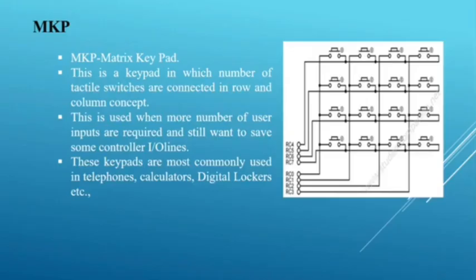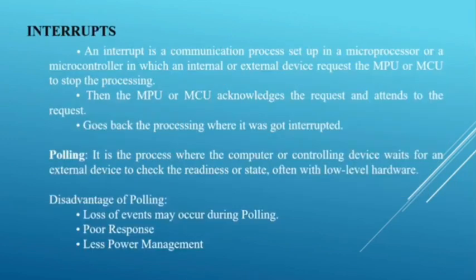Next, MKP, matrix keypad. This is a keypad in which a number of tactile switches are connected in a row and column concept. This is used when more user inputs are required and you still want to save some controller input and output lines.